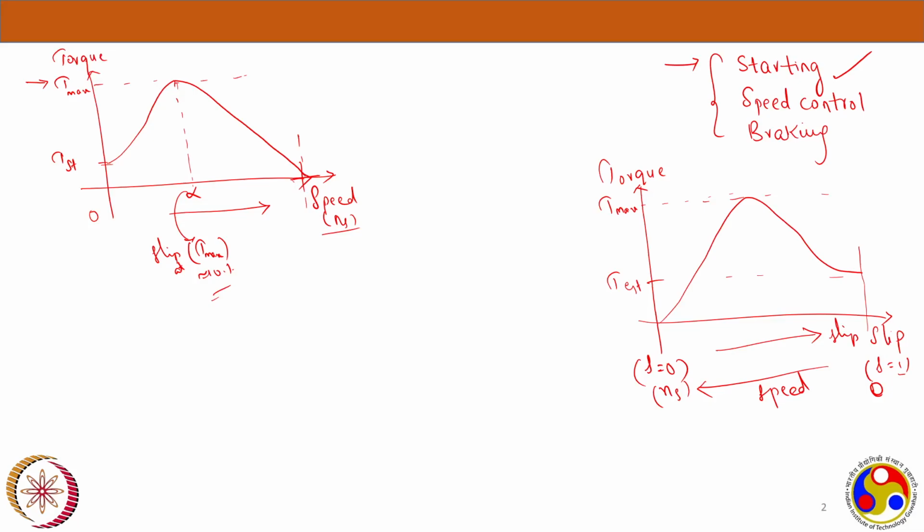Now, if we have a motor having torque slip and also torque speed characteristics like this, say we have a load requirement. This is the motor curve. For whatever load you are using the motor, it is going to give this kind of characteristics only. This is how the motor would behave for this particular speed. This is the torque it will give. Initially it will give that much starting torque, and as the motor picks up speed, that is the torque profile it would give.